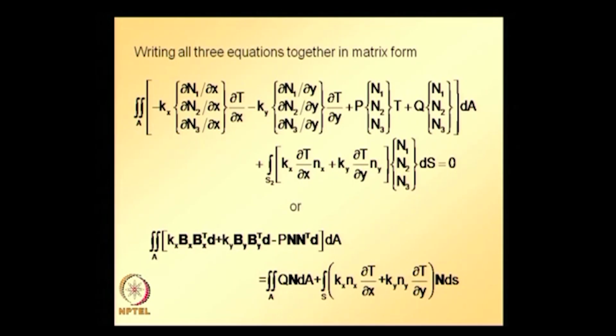I gave a detailed explanation in the last class. We can write this because the integral over S1 is unknown, and there is no need to evaluate it since the corresponding nodal parameters are known. That is, the essential boundary condition is specified, and equations containing these terms can be removed from the system before solving for the unknown nodal parameters.